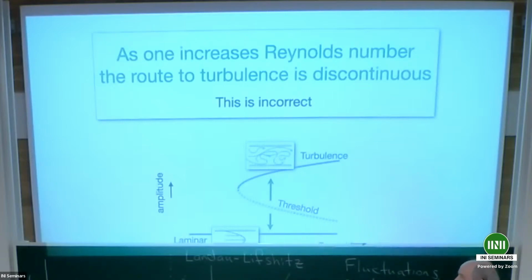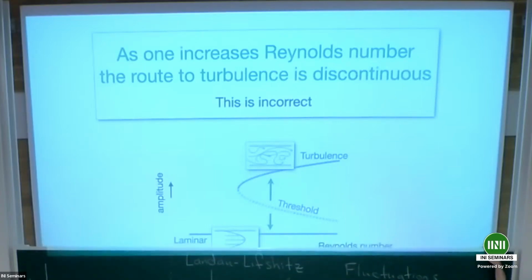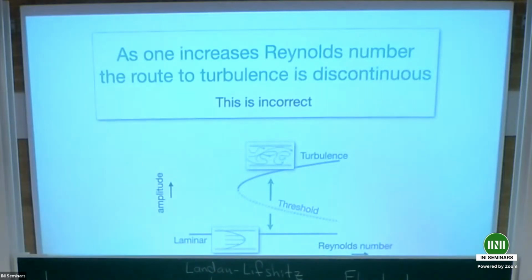In terms of developing models, you realize that it is not just about turbulent and laminar, but there's a mean profile that is involved in the flow, and that acts as a slow field. What you have is a turbulent field, which is a kind of fast field, and coupled to it is a slow field, which is the mean flow. And it's that coupling which sets the scale of the pattern that we know. And how it sets the angle, we still don't know, but we're getting close to being able to answer that. Okay, so these were the things that were missing.